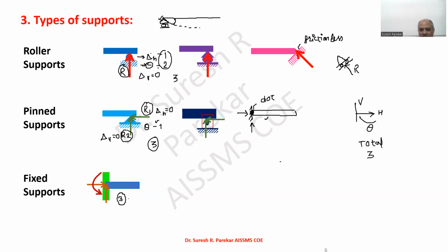Only two exceptional cases in which displacement and reaction are simultaneous. One is spring and the second is sinking. In these two cases, we have a reaction and a displacement, both simultaneous. So we have to keep in mind that if displacement is restricted, then only reaction will be developed.